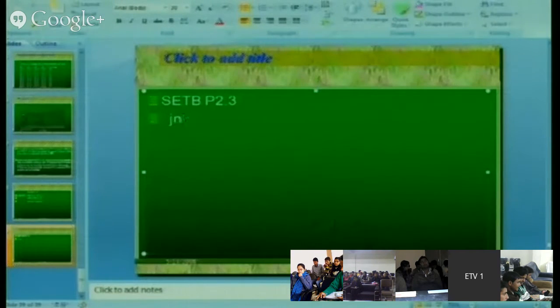JNB. Tell me the label. Let's say here. Jump if not bit P2.3, comma, here. See what this will do: it will keep on monitoring this bit P2.3. Jump if not bit means, if it is low, jump to here, and here I've kept it here only. So till the time your P2.3 is low, it will not go to the next step. It will remain here only.